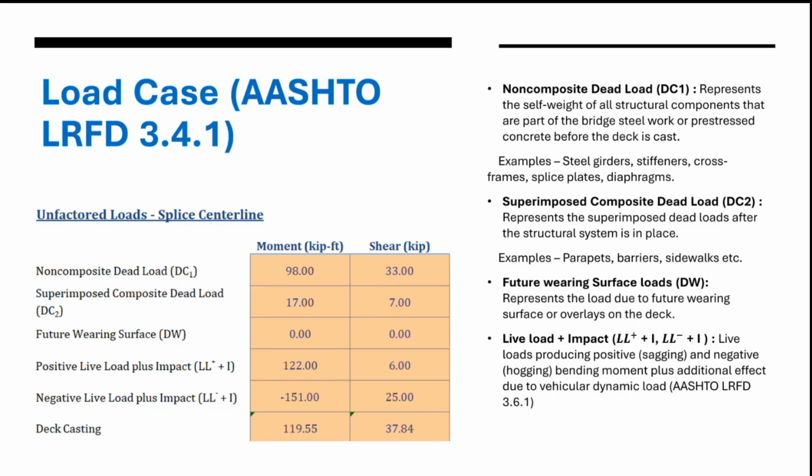So Ayush, the question from Mansoor was that the splice plates you are designing are for the moments and shear you are getting from the superstructure, right? He is saying that there are some design manuals which require you to design for the moment and shear you're getting from the superstructure, but also to somewhat match the capacity of the girder, the flange plates of the girder that you have.